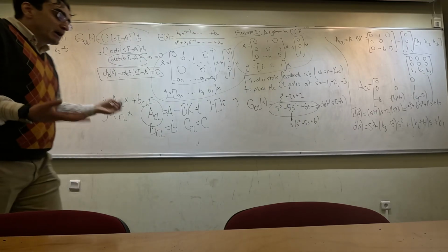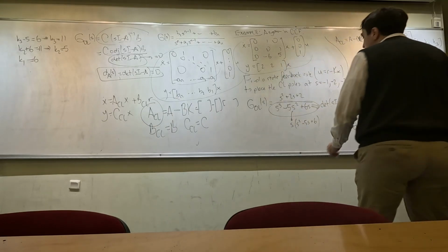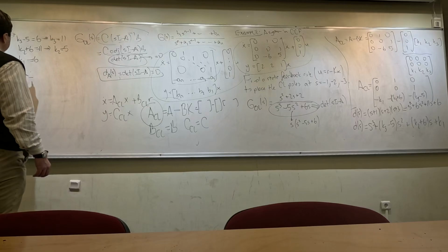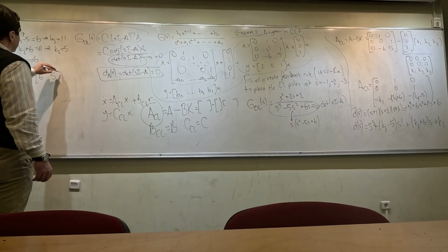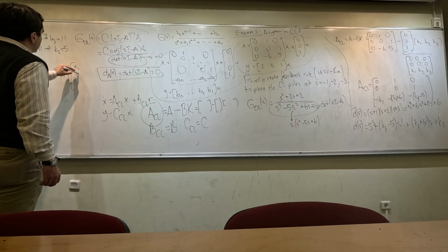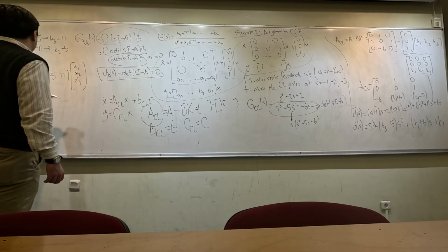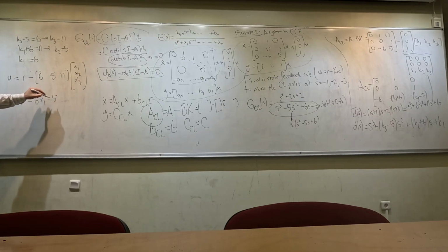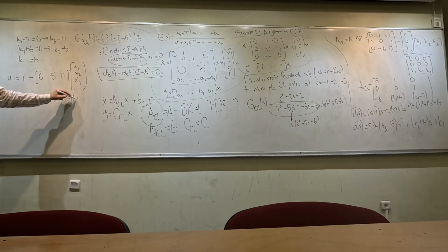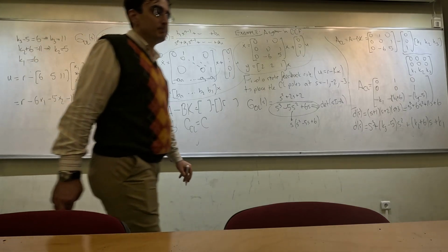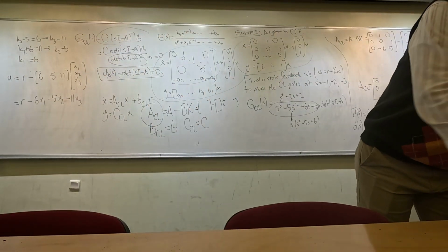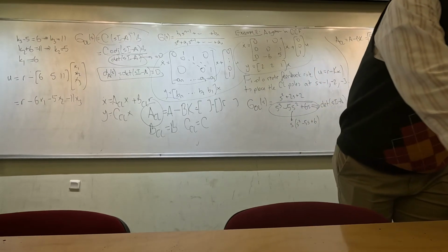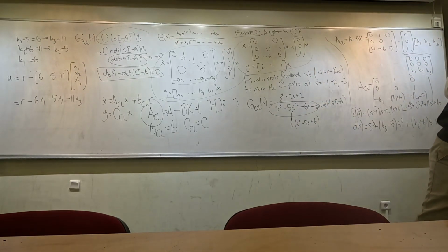Okay? So that actually means that for this system, the state feedback rule is u is equal to r minus k, which is [6, 5, 11], times [x1, x2, x3]. Or if I write this explicitly, minus 6x1 minus 5x2 minus 11x3. Any questions?